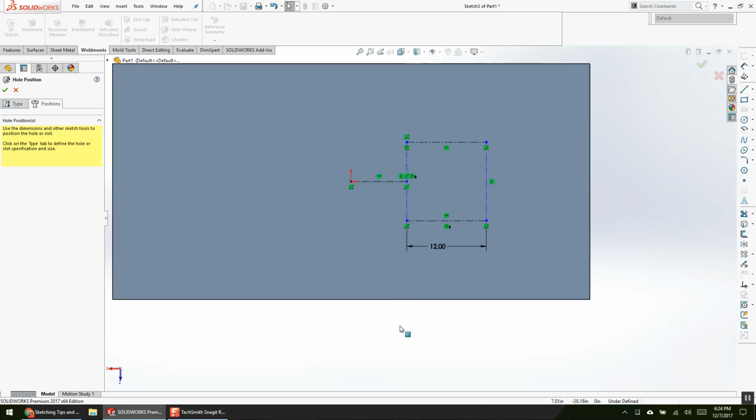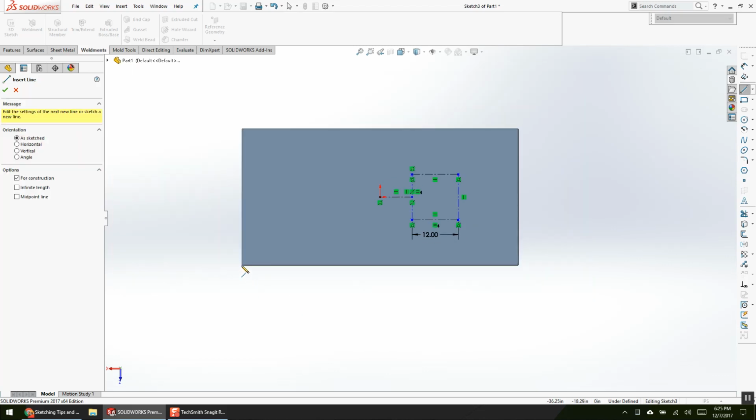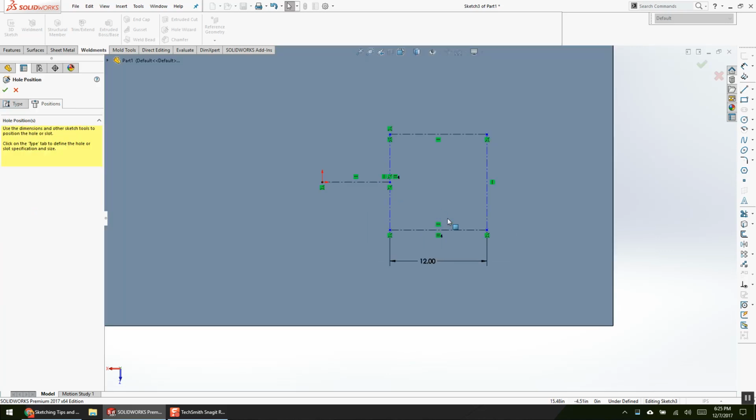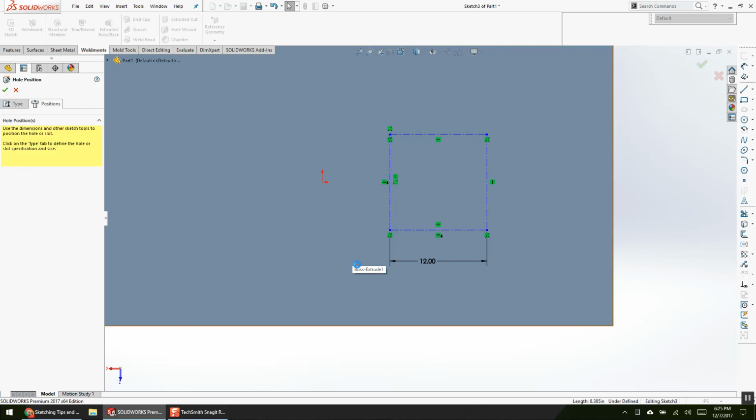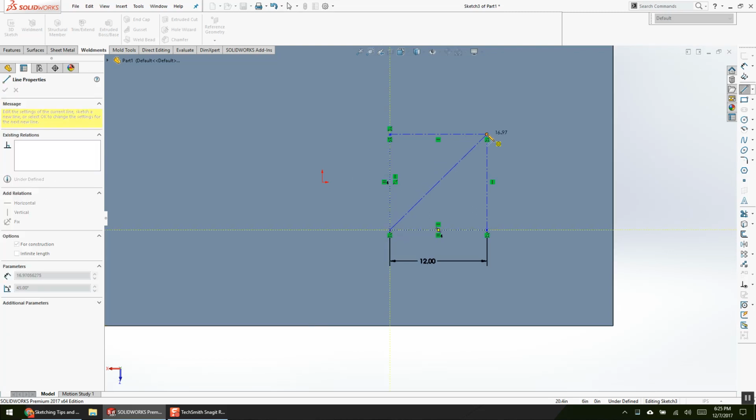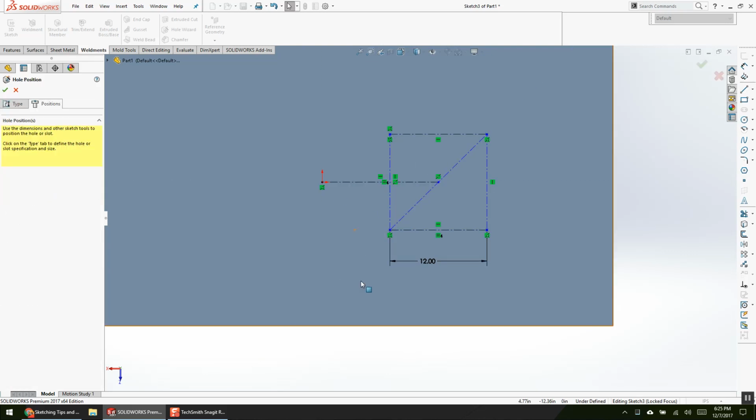So we've got that. Would you be better to have a diagonal going across and you use that? Now you've got a distance. In your sketch that you have there of your whole location, get rid of your line that's in there. All right. Go from the bottom left corner to the upper right corner. Okay. Now from the midpoint of that over to the origin. Yep. So perfectly acceptable. Accomplishes the same thing. I'm not arguing with that. It's one extra line that I'd rather not draw because I'm an incredibly lazy person.